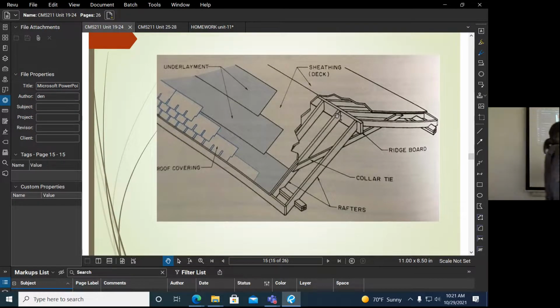So whether this is a truss or whatever, up above, the roof is going to be in a similar configuration. You're going to have the sheathing, roof decking, which is usually 5/8 plywood. Generally, you can use chipboard, but it's not very good to use chipboard for your roof. But you can save costs by doing that. I still recommend plywood, marine grade plywood, because it's the roof. It's going to be exposed to a lot of conditions.